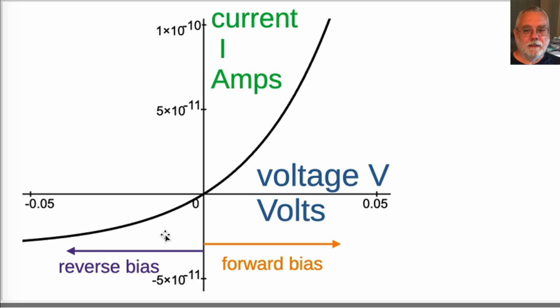The amount of heating depends on the amount of power. A voltage and current in the lower right or upper left quadrant with this current convention would represent power generated by this diode and sourced into the external circuit. But this ordinary diode cannot generate power, and the IV curve does not exist in those quadrants.